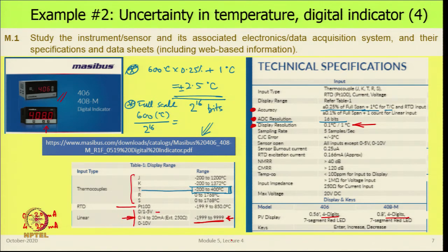So, if the temperature indicator was transmitting a current signal, we would use this. What we will do is we will directly connect our temperature sensor to this indicator and see what happens. So, we are not wanting to get into this part for now. But in the real world, this is how things will happen. One will have to work with one of these things because the distances would be long. You do not want signal attenuation, and so that is what you do.